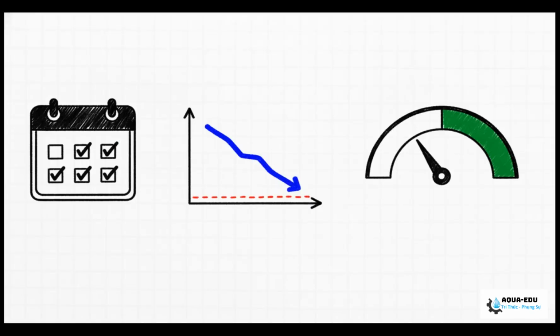So, when can you finally take a breath and relax? Well, you can officially declare the incident resolved when your nitrate stays strictly under 1 milligram per liter for 3 days straight. Your total nitrogen is fully back in compliance with your discharge permits, and your overall denitrification efficiency is restored to at least 85%. That's when you know you've won.